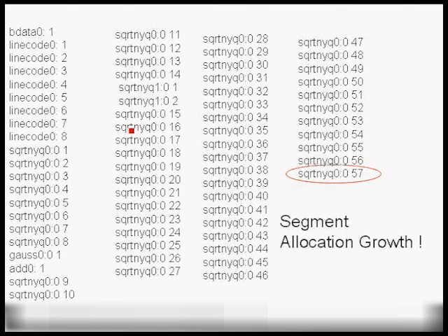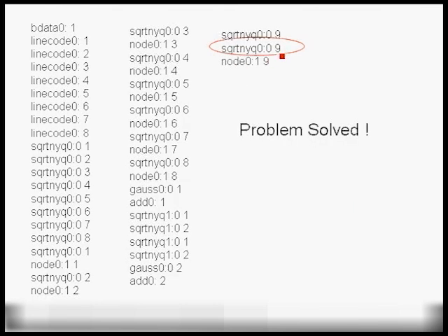This is the result of buffer.dat when we did not add pacing, and we saw that the buffer actually grew to 57 segments because of the pileup, in the case where the add block only processed 128 samples at a time. So compare this situation to this situation, and we see that the buffer on the square root Nyquist filter is bounded, and we've solved the problem.